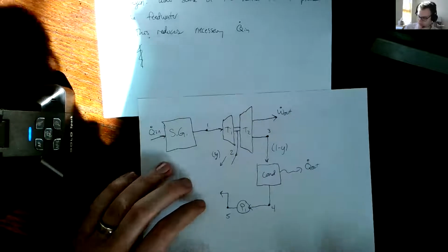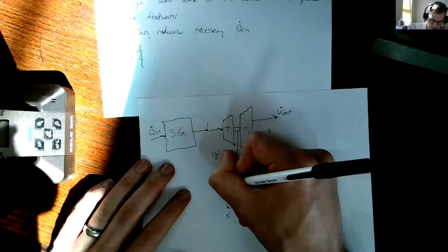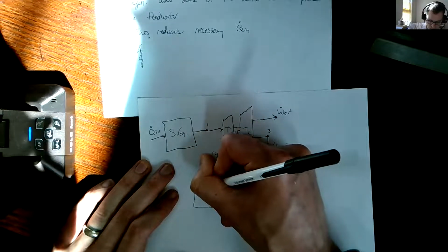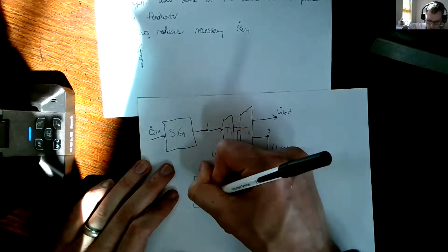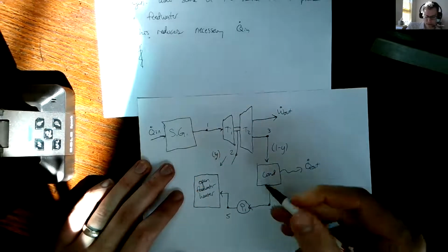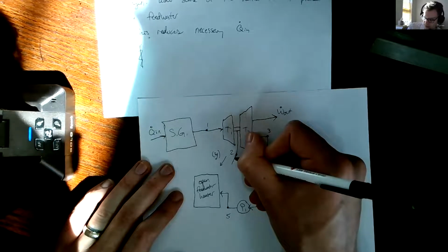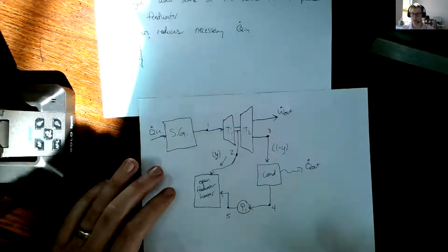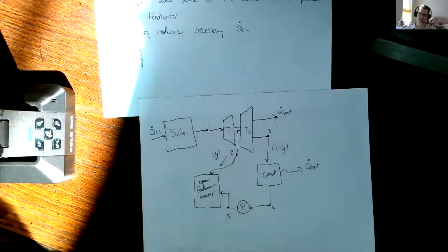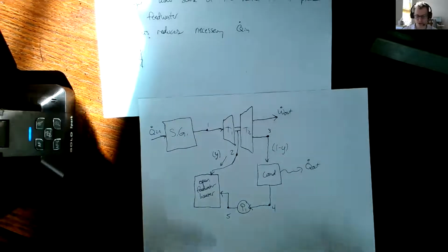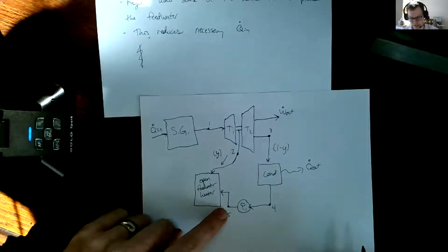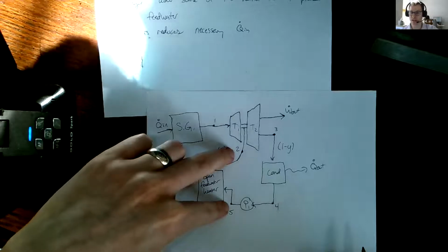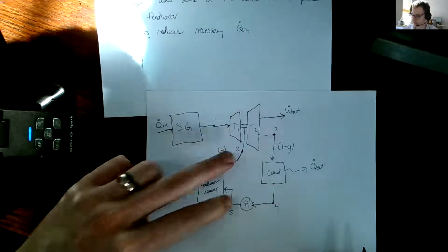And in this case, we're going to use something called an open feed water heater. In an open feed water heater, all the streams coming in have the same pressure. It's just like a big open tank, and we're just going to mix everything together, so they all have to be the same pressure. That's why we need this pump, to kick the pressure from state 4 up to state 5 to equal the pressure coming out of that first turbine stage at state 2.